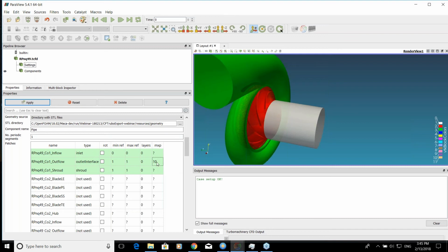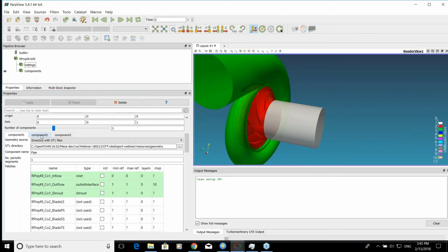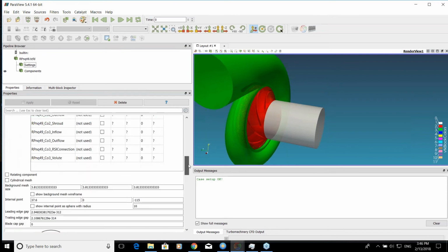Here, using this value, you define how many strips or rings will be used for averaging. If you set 0, the standard arbitrary mesh interface is used, which in CFX, for example, is called the frozen rotor type. And if you enable this mixing plane approach, I think it is usually called the stage in CFX. This is done for each component.